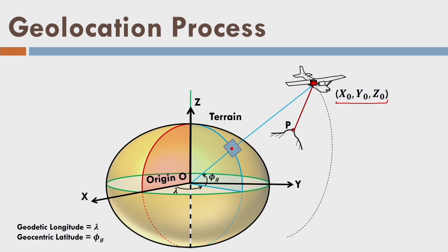This is the local geodetic horizon, and I have defined here the 3 directions: true north and true east, or the geodetic north and geodetic east, and the gravity direction. We have made an assumption that this direction is gravity, and it is a fair assumption. So, this is true north, true east and gravity direction at the GPS.